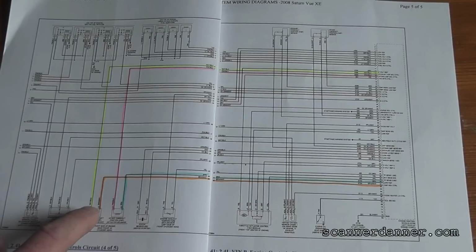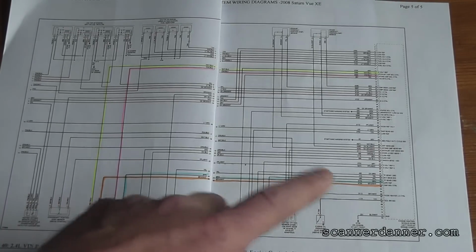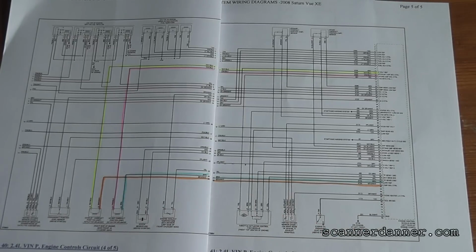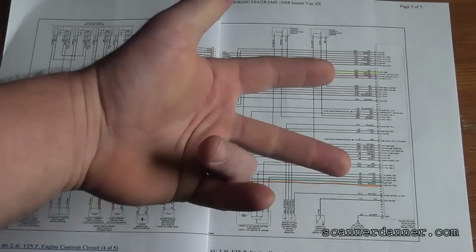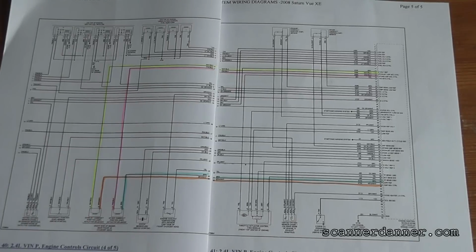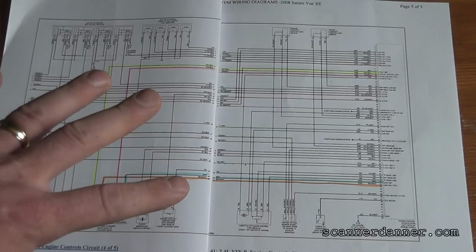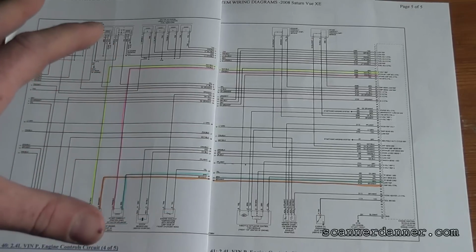If one of these two wires would be going to an external fuse, that means the wire going to the computer would be ground side switched. And in this case, we cannot make that identification using the wiring diagram. Both wires go to the computer. Now in the past, what I've said is every time we see this, it's a power side switch circuit.